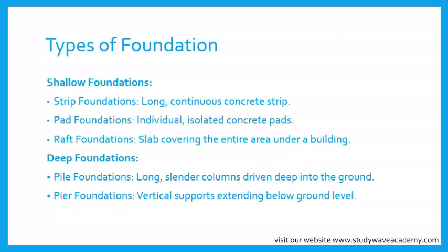Good. Then the deep foundations. The deep foundations are like the building's shoes going deep into the ground for extra support. And there are two types. Pile foundations. Long, slender columns driven deep into the ground. They look like long columns in the ground, and the purpose of the pile foundation is strong support in areas with soft or loose soil. Okay?